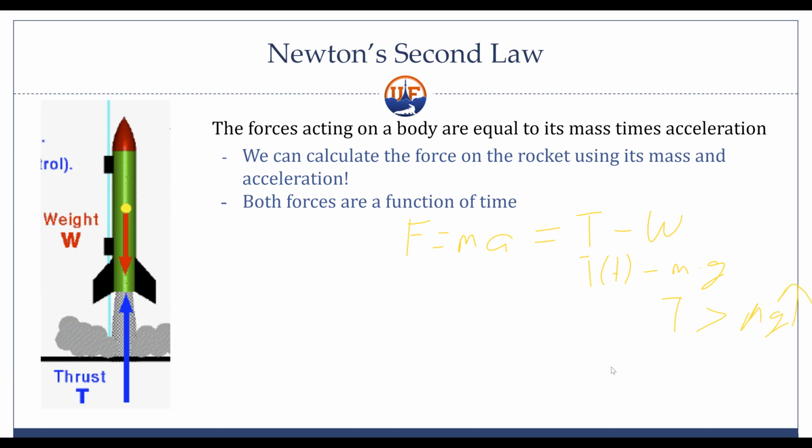Once we know that, we know what type of motor, what size or what power motor we need to use. Something to keep in mind is that this mass is not going to be constant. It's actually going to decrease as the propellant is used, and that's going to decrease the mass of the rocket very minimally. So you don't really have to consider it that much, but it's something to keep in mind that they're both functions of time in that sense.